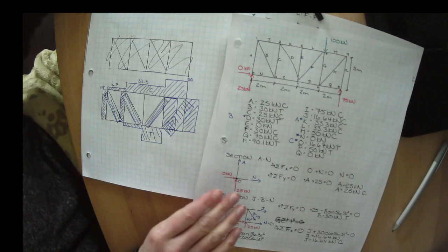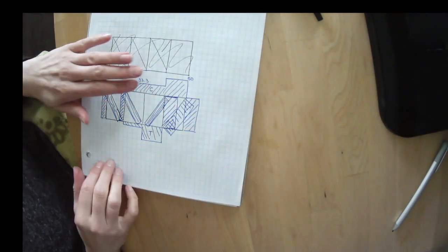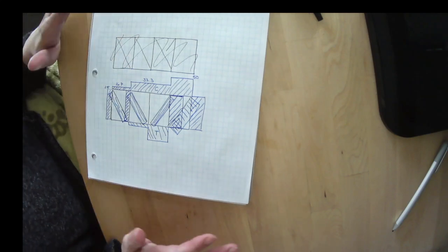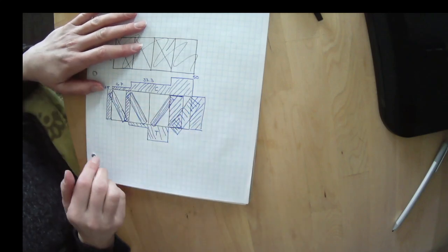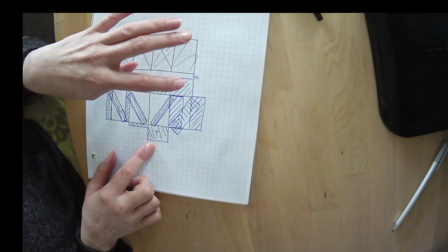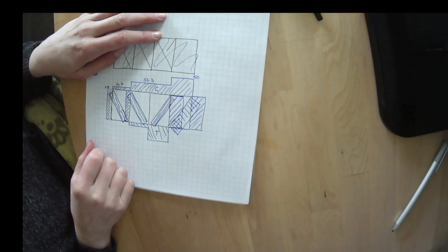Now, I know it looks messy right here. Sometimes what we'll do is maybe do two separate diagrams where one is the top chords and then one is the webs. But what's nice about this, and I didn't draw it completely to scale with the webs here, but it's really nice that you can see, okay, at a glance, here's where the worst compression is in my top chord, and here's where my worst tension is in my bottom chord.